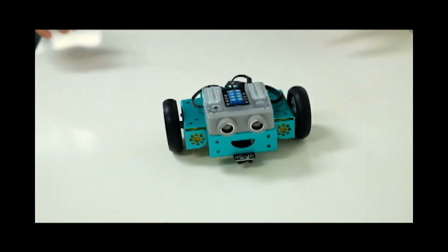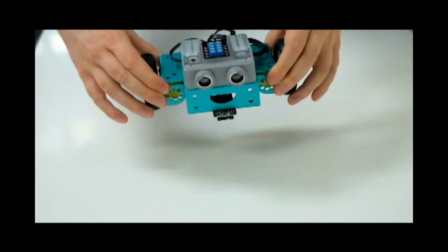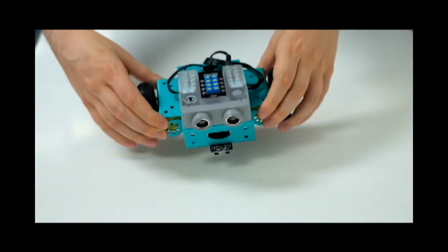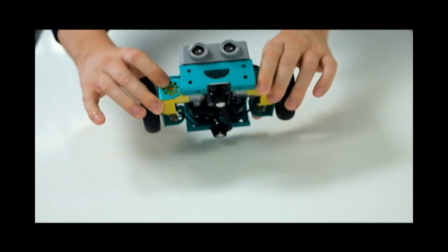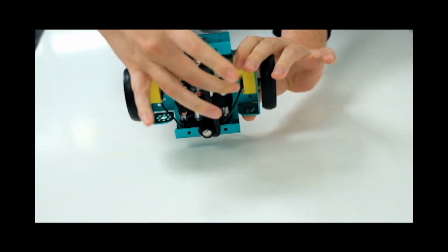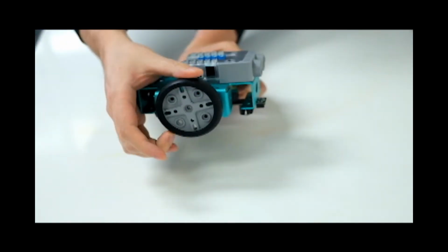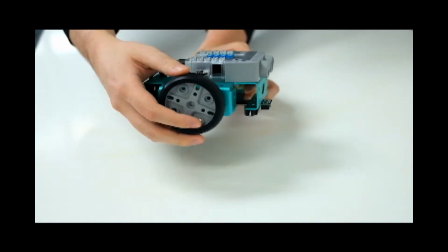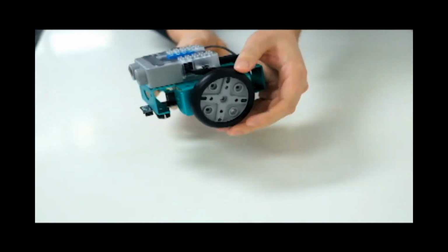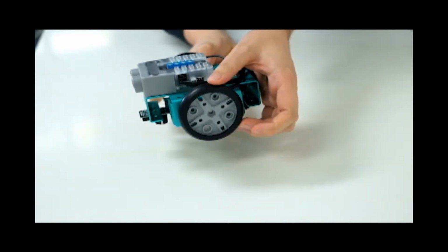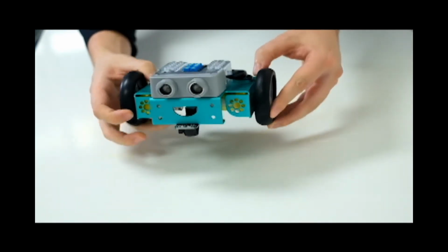The chassis needed to be adaptable to these additions, so we have ensured this is the case. The FlipRobot starter kit is a wheel-based robot because it provides a good introduction to coding movement. Each wheel is powered by a DC motor, meaning each wheel can be individually programmed. This setup allows students to not only become familiar with wheeled movement, including single and double wheel rotations, but also with calibration, as the motors will need to be programmed to run at the same speed and same direction.